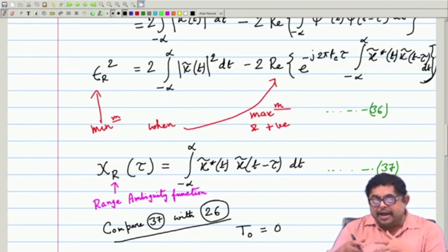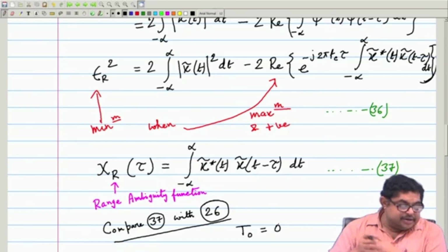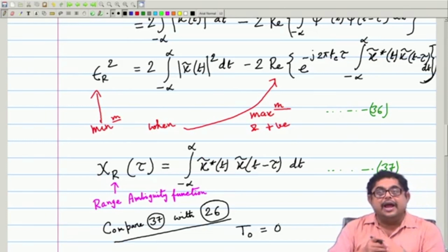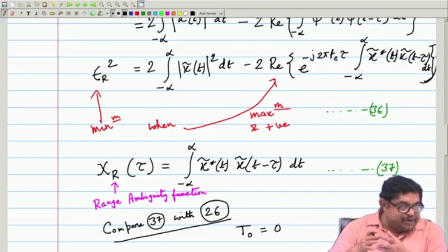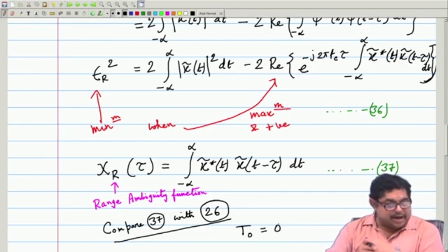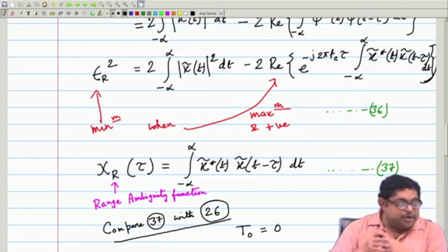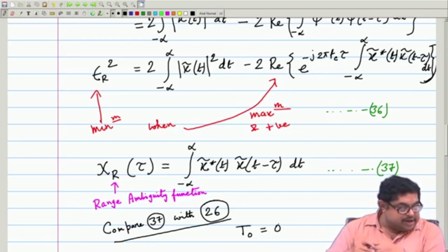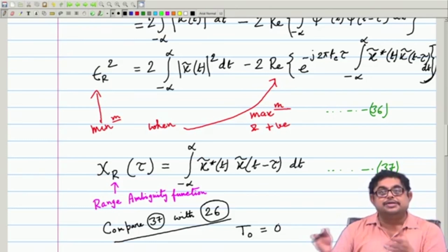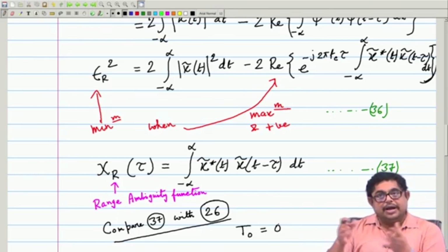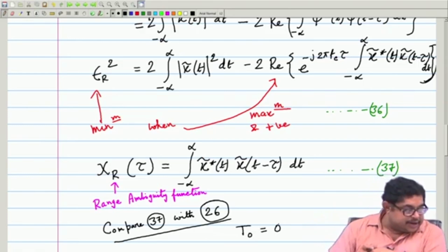So, you will see that they have the same envelope, but different phase. This indicates that the matched filter not only provides maximum SNR at output, it also preserves the range resolution characteristic, because I can resolve range by this, I can separate two targets by this, etc.